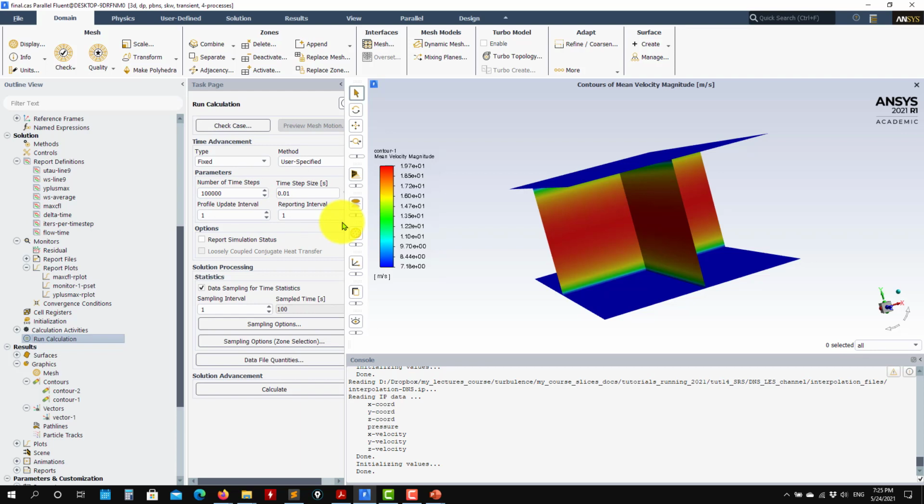In the LES, we know that it's extremely recommended to have a CFL about 1. So this is a rather large value. If you run this one, I'm not going to run, but if you run this one, you will see that your CFL will be really high, but the URANS doesn't have problems. So you can do that. See that this was run for a really long time, 100 seconds to get all the statistics.